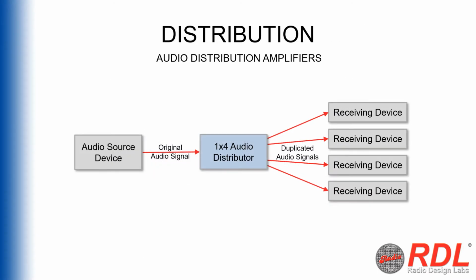Audio distributors, also known as distribution amplifiers or DAs, duplicate input signals into 2 or more identical yet isolated output signals. This function allows one signal to be distributed to multiple destinations for a variety of purposes without inducing unwanted noise or signal degradation. Some distributors may include input and output level adjustments. Since signal level strengths can decay over long runs, individual output level adjustments are especially useful to balance the final signal levels at their destinations. Distributors can be designed to support mono or stereo signals, balanced or unbalanced signals, or both.